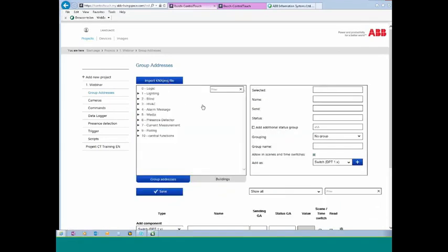In our case, I also want to add some scenes. Maybe your electrical installer has already defined several scenes in the ETS projects. You have a lot of possibilities for how to organize the scenes. First, you can say, okay, I have some scenes stored in other KNX devices, in some actuators like this. That means you can use the ControlTouch as a so-called extension unit.